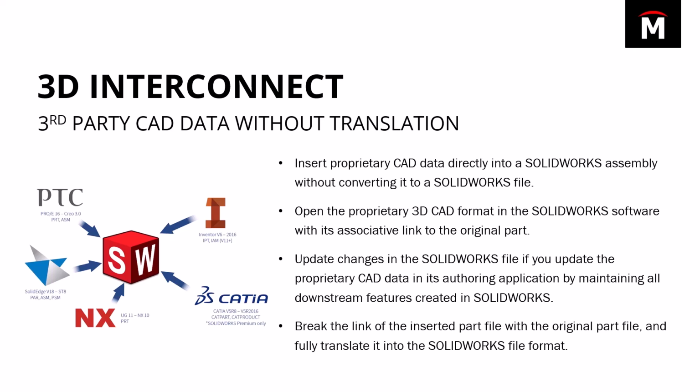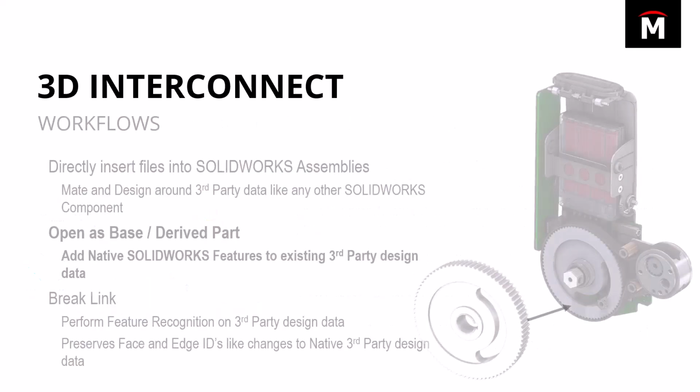You know, if somebody is working in another proprietary CAD program, there's no way to edit the features of that program, right? The only thing that can edit a SolidWorks feature is SolidWorks. And that's the same with any CAD program. So they might be saving to a STEP file and sending you that. Tell them not to do that. Just have them send you the native file. I'm going to show you this process with Creo files, so the PTC file here.